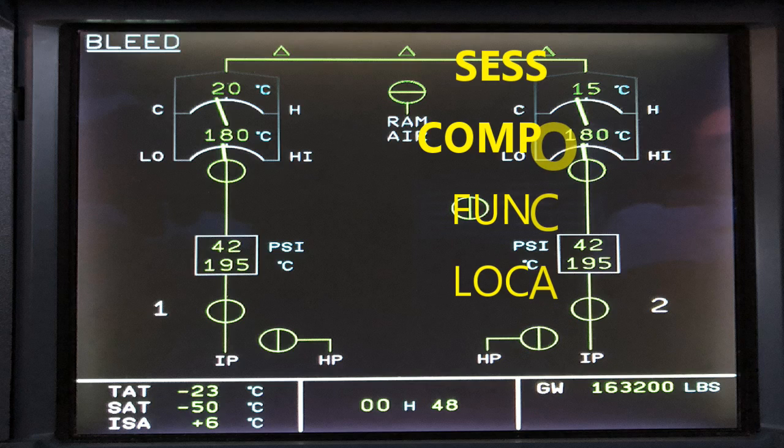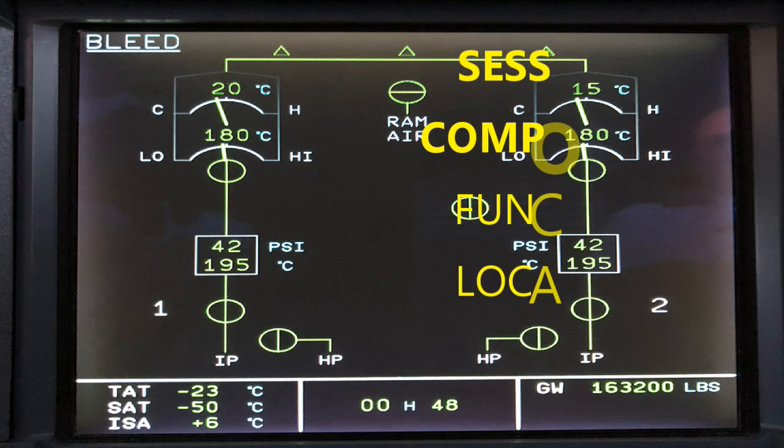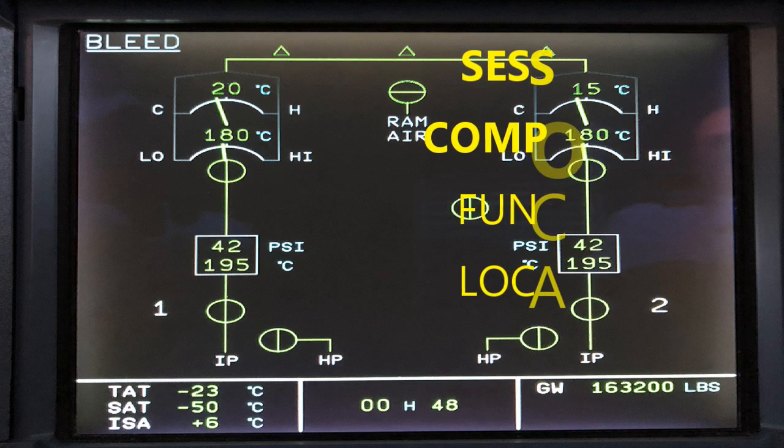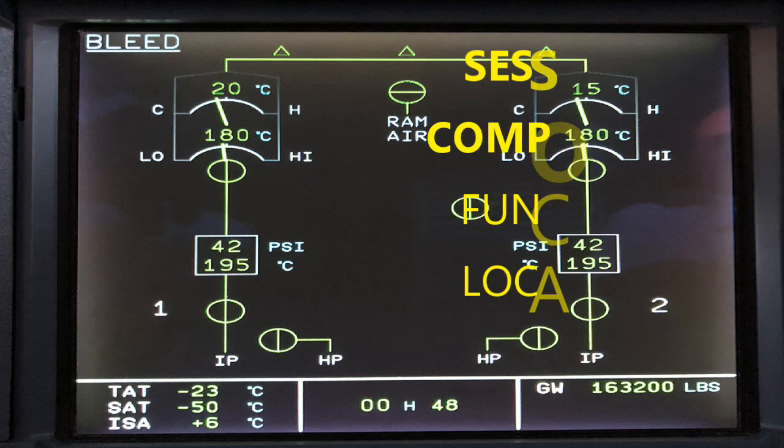At any rate, when the engine PRVs close, then the cross bleed valve opens, and that's going to happen automatically when the APU is the one supplying the bleed air, because when the engines are no longer there to provide it, it's going to be coming from another source. In this particular case, I'm talking about the APU, right?